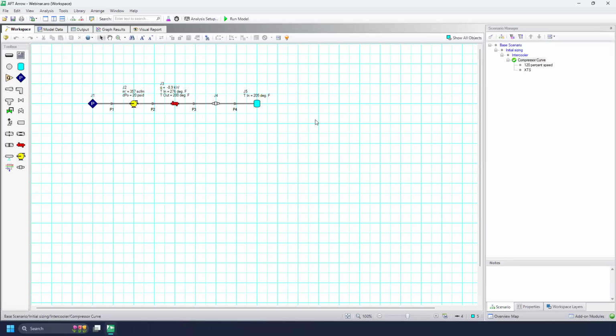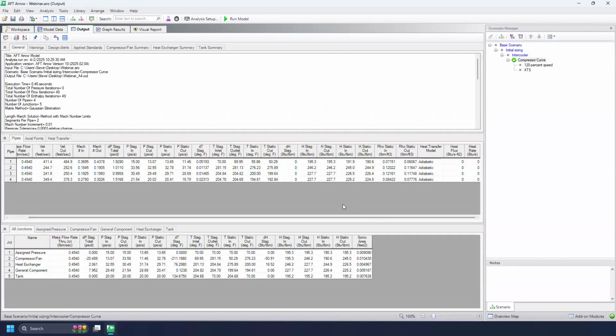And that's why the equations I showed earlier were a little misleading, because again, those are a simplification of what's going on. But yeah, we can see here that the stagnation at the outlet from the heat exchanger is at 227.7 BTUs per pound mass. And we're seeing the same thing once it's going into the tank here. So that is what we're expecting to stay constant for that conservation of energy, and we're seeing that it is constant.